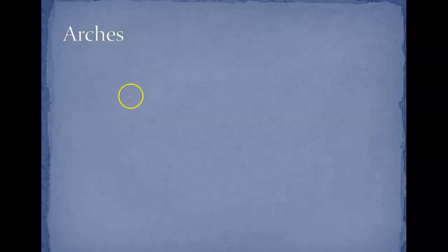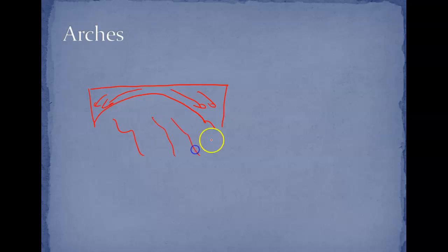So if we think about arches, some old bridges, you may have noticed, even though they're flat on top, they're built kind of like this. Sometimes even today. What that's doing is the load that's here is being transported just through the nature of the structure over here. Now we've got water usually running through here. This is where the bridge is being supported, and so all the weight is coming over to where it is on land, as opposed to being held just straight here. And so an arch can be a very effective way of doing that.